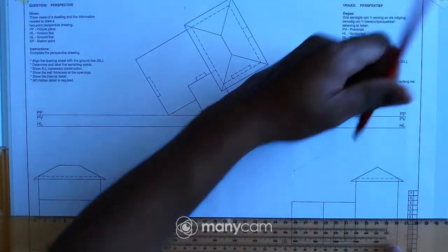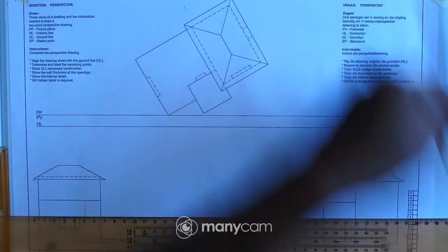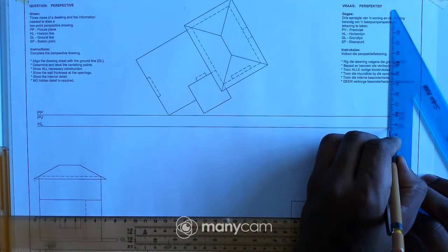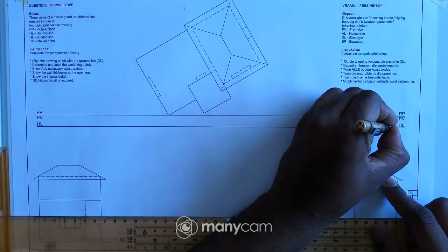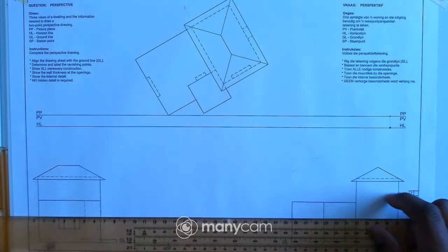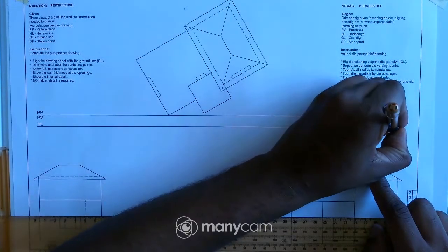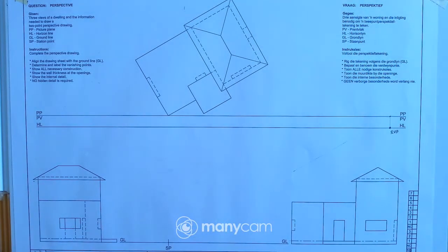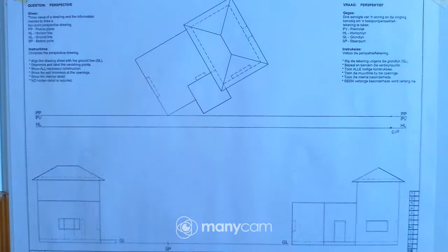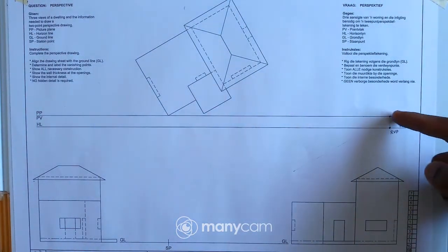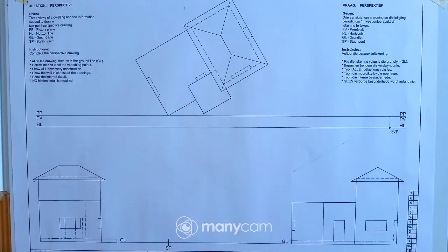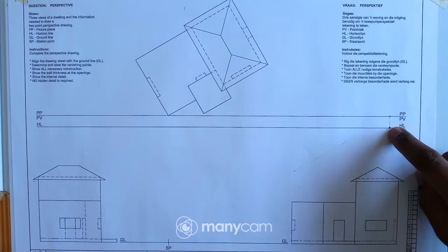and from there where the line intersects with the picture plane, I'll have to drop that point down to the horizon line. So the vanishing point is right there on the horizon line. So this is my right vanishing point. So please make sure you label the point. So obviously you draw a line from the station point up to the picture plane, and from there you just drop that point down to the horizon line, because the two vanishing points are always on the horizon line. Okay, so this is my right vanishing point.